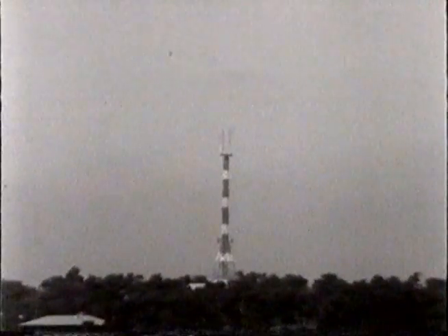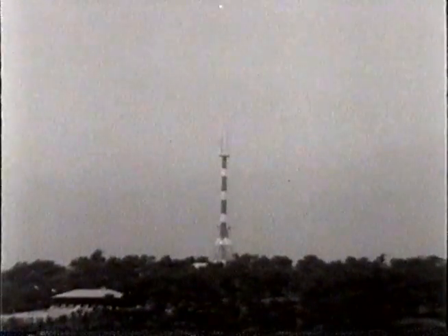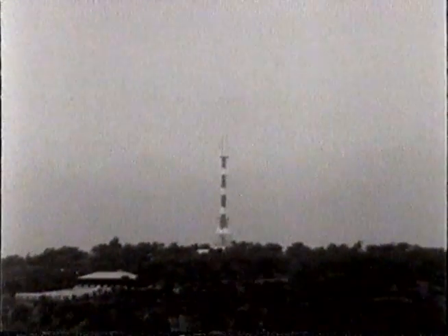On the ground as well as on the aircraft, the antenna site is a very important factor in helping the efficient functioning and clearing of obstructions with the maximum radiation of signal energy. It is vital to have the transmitting and receiving antennas elevated as high as possible above the ground. But it must be remembered that their high elevation increases the hazard to aircraft.